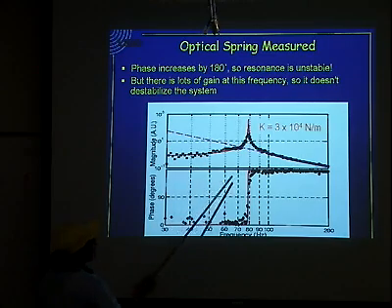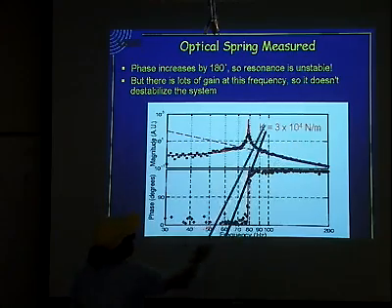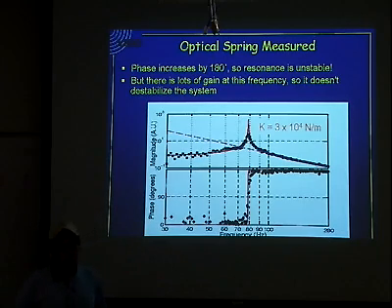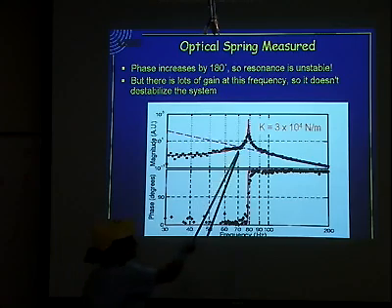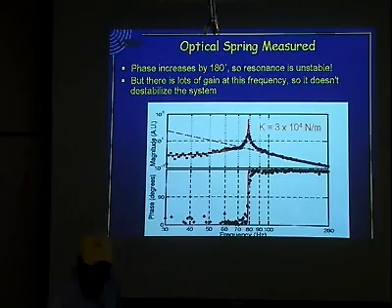And you can also ask, when you move this 1 hertz oscillator to 80 hertz, this is what we've done, in this case, this corresponds to a spring constant of about 3 times 10 to the 4 newtons per meter. Now, if you want to put a scale on that, if you take the optical beam, the actual laser mode inside the cavity, and if you made an oak beam made of the same dimensions, you would get that rigidity. Except, of course, oak would give you a lot of noise.